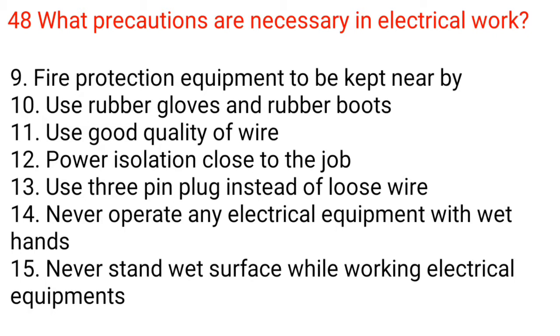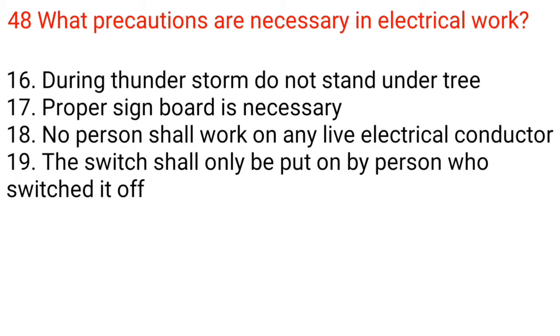14. Never operate any electrical equipment with wet hands. 15. Never stand on a wet surface while working on electrical equipments. 16. During a thunderstorm do not stand under a tree. 17. Proper signboard is necessary. 18. No person shall work on any live electrical conductor. 19. The switch shall only be put on by the person who switched it off.